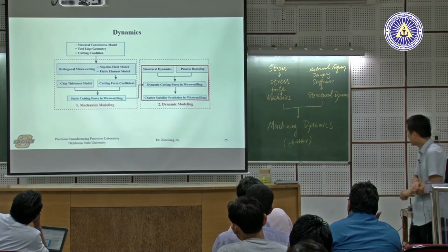Your cutting force coefficients that you get in micromilling, can we get them in milling and then use them in micromilling for the same workpiece combination? No, right? Because there's no tool effect. So we have to identify it separately, because the uncut chip thickness which you are cutting, the size effects will be there.